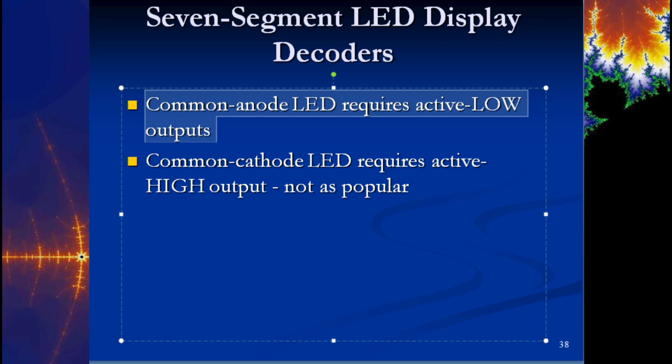So if you leave all of your inputs high all the time, then you're going to know if something drops out and becomes low. Whereas if it's active high and you're at a low, any noise on that line could possibly push that up into a high. But if you get noise on something that's active low, then you can't get higher. It's already high, and so if you have a little bit of noise on top of that high, it's not going to change the state. And so that's why we prefer to use active low outputs, and why we like to use negative edge triggered flip-flops.